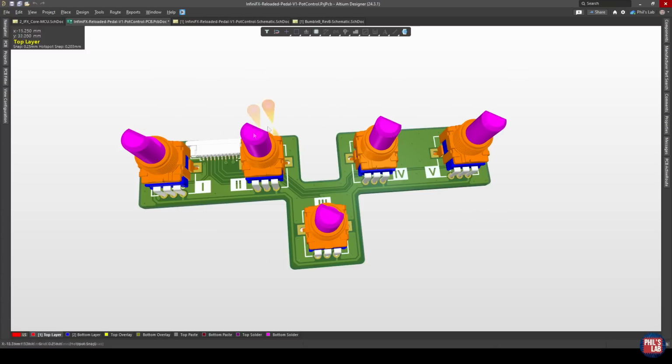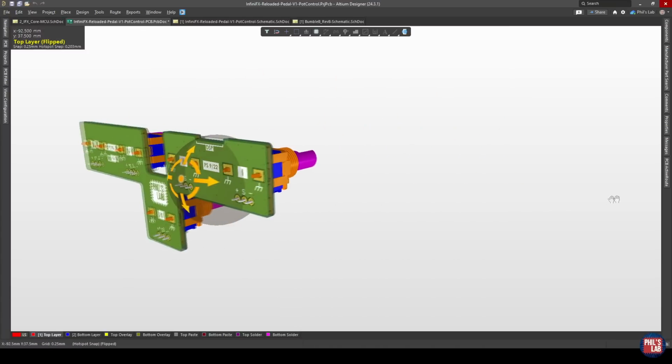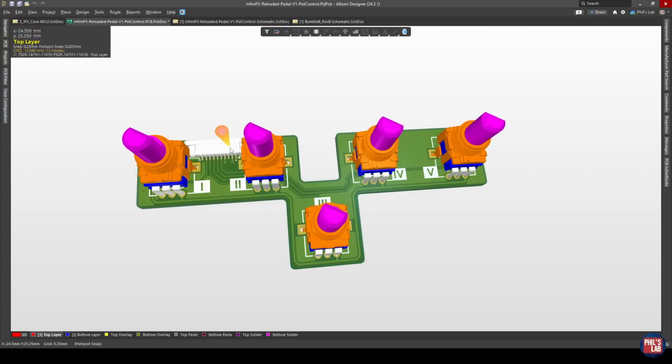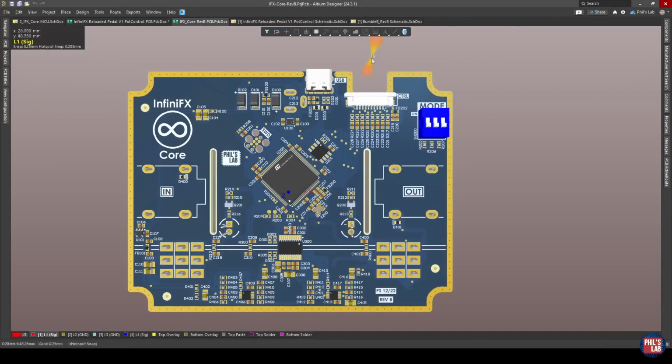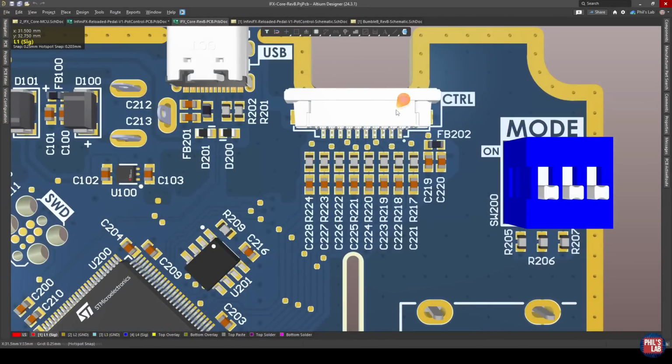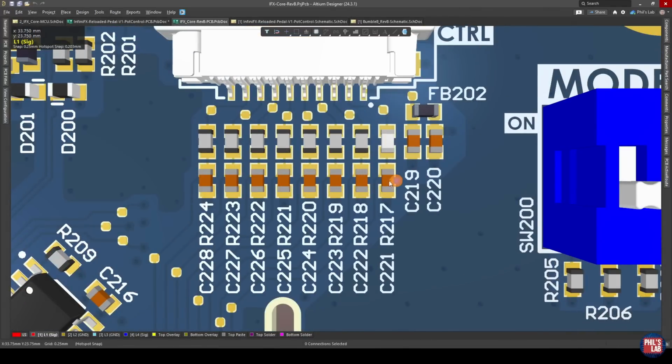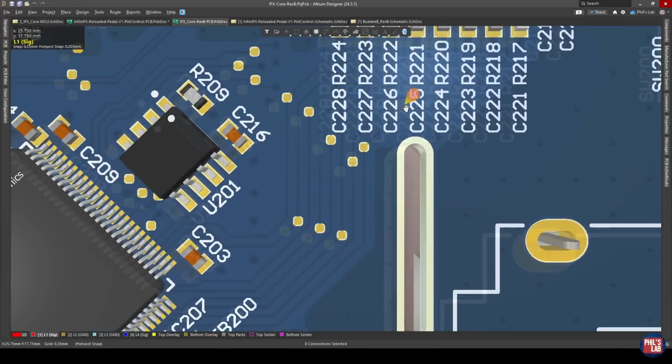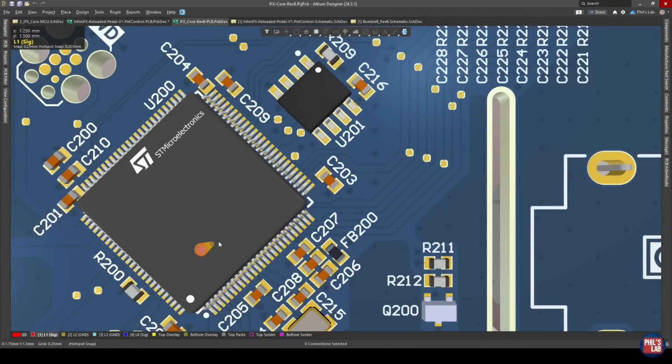So our potentiometers are located on the board we saw in the picture previously. There's nothing else on this board other than the potentiometers and a ribbon connector, so we connect this up to the carrier board. On the carrier board then we connect up our ribbon cable to this ribbon connector, and as we can see here then we have these RC low pass filters which then feed into the STM32H7 pins that are hooked up to the ADC channels.